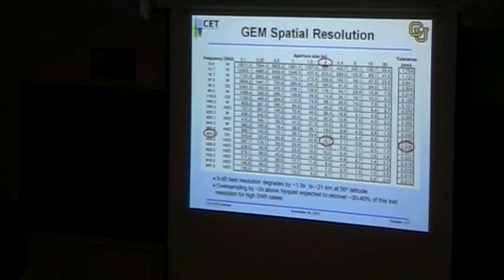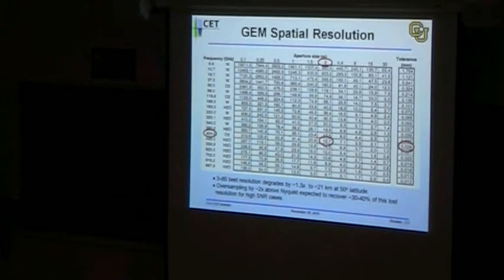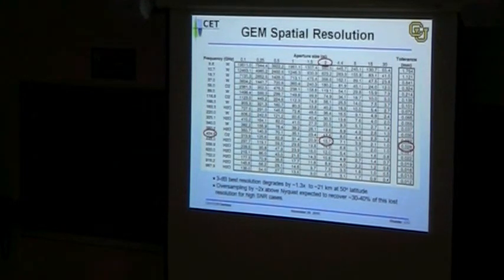But what are the problems in going to geostationary orbit? One of the biggest ones is distance. At roughly 37,000 kilometers from the surface, any antenna beam that you have expands into a rather large footprint. And so you have to have a very narrow beam to be able to observe anything at these scales that we're interested in, 10 kilometers, 20 kilometers. And therefore, if you're working at microwave frequencies, where the wavelength is much longer than the infrared or visible, you've got to have a big antenna. And that has been a major cost driver ever since the idea of going to geostationary with microwave was explored.